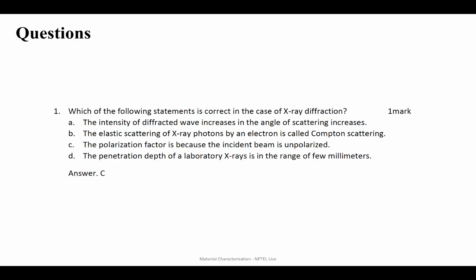X-ray diffraction spectrum. And let's say instead of a glass slide, you use a crystalline material like a silicon wafer. Now, when your X-rays go deeper into your silicon, they will experience another lattice, so from that lattice they will also give out peaks. So the resultant will have peaks from your material as well as your silicon substrate. So you will have to figure out which are the peaks from your material and which are the peaks coming from your substrate.